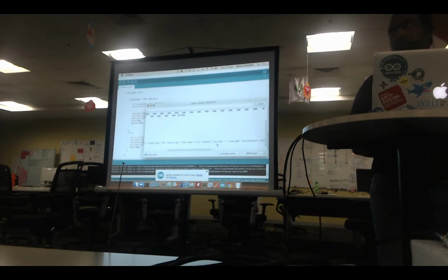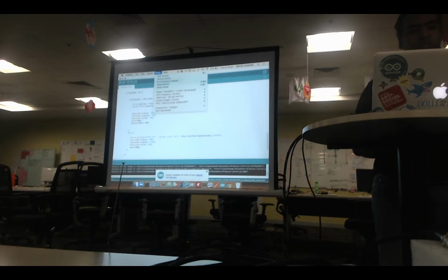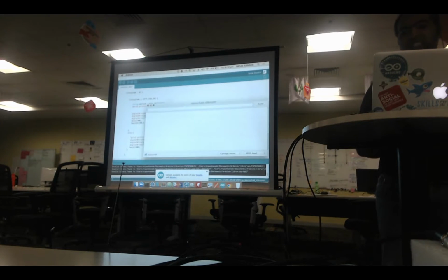Right? I don't understand. So you paste the URL from the browser. No, I didn't paste it from the browser. I pasted it from the serial terminal. So the serial terminal is something which enables the communication between the computer and this. It opens it as a serial port. If you see, I have opened it as a port here. So this is connected to this device. And to connect to this device, I open a serial monitor. In the serial monitor, it will start communicating with this device.